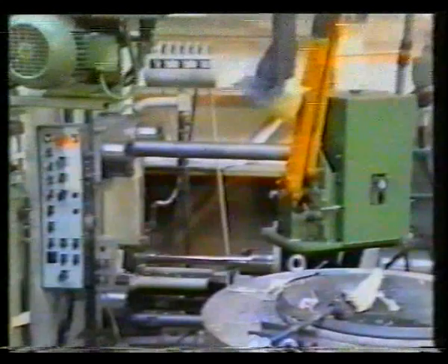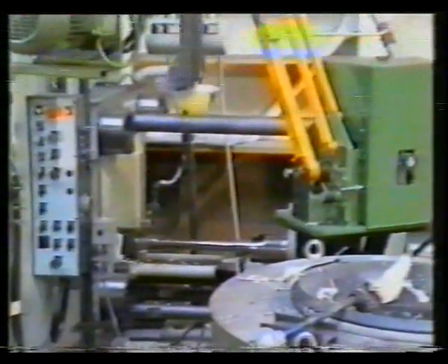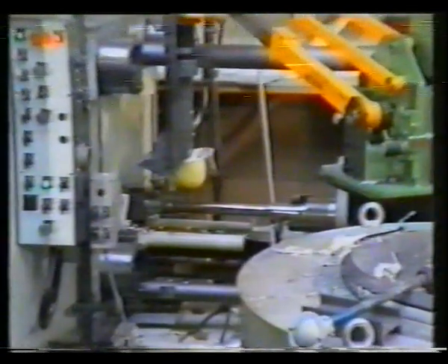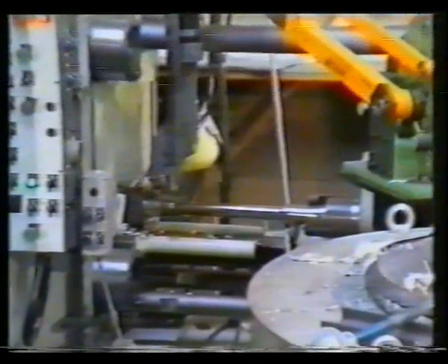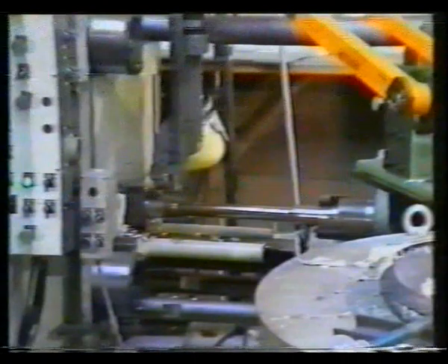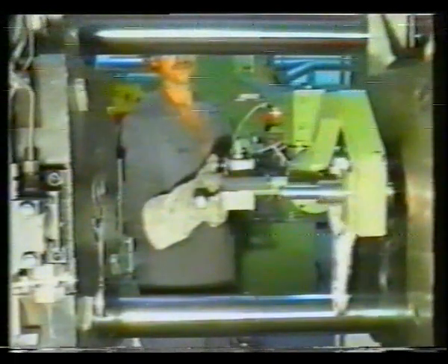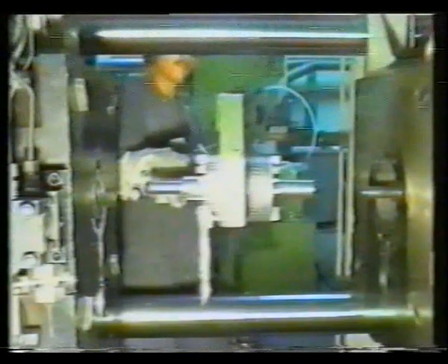Conveying of the molten metal by fill mat. And when the die is closed, ladling of the molten metal into the machine and shot. The production rate here is 26 to 55 shots per hour, with different size castings being produced.